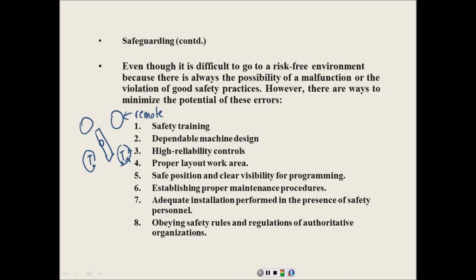We call it teach. Some of them call it auto, some of them call it play. That is the mode. You switch that robot in, and now you've turned that thing over to a program. While you're in the manual mode, even though you can run programs in manual mode, you're going to be limited in speed. It's just that on the Kuka, when you set 30%, it will now be 30% like everybody else's. So be careful and don't put it on full speed. Don't put the speeds up to 100% on that robot, because if you do, it's going to run at 100%.